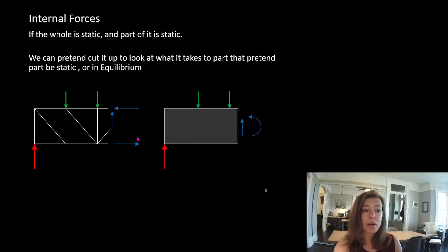So instead of drawing that as a bunch of unknown axial forces, we could draw that as the unknown shear force and the unknown bending moment holding this object in place. So that's exactly what we're going to do. It's the exact same system we employed for solving for trusses. It's funny, in some ways people find this part easier, even though sometimes it looks more complex.